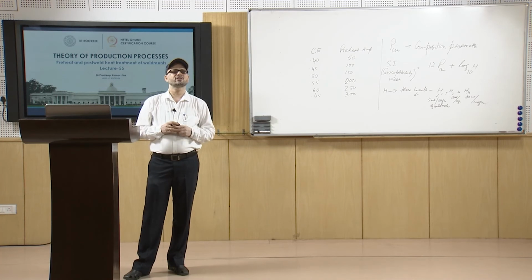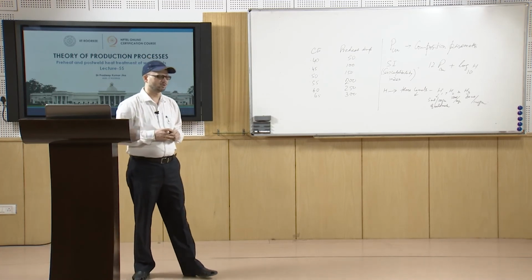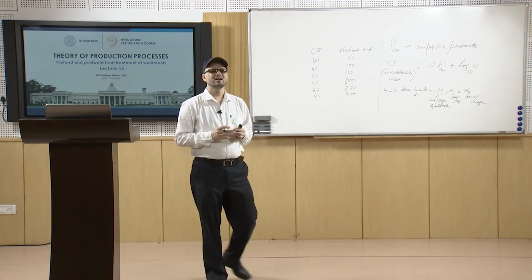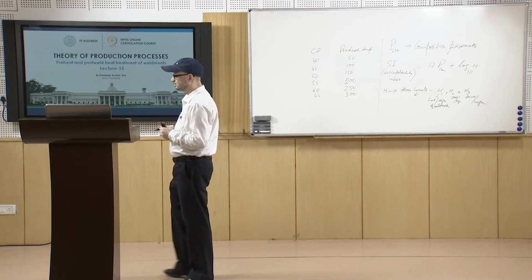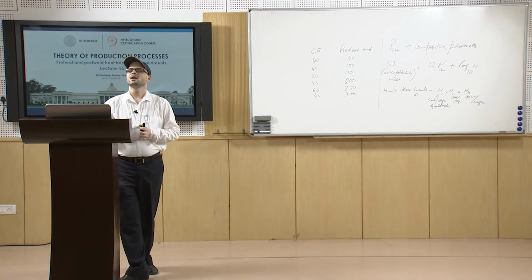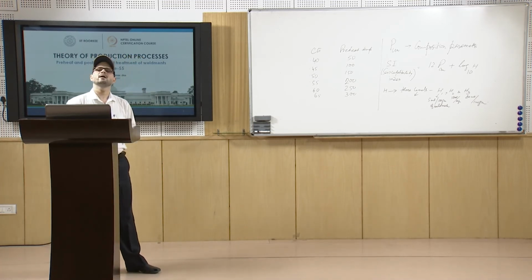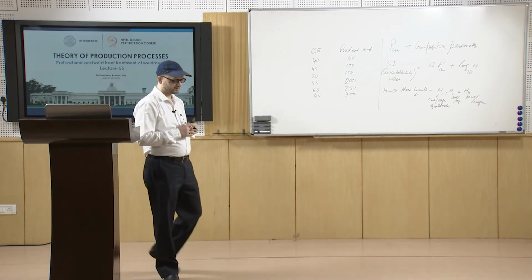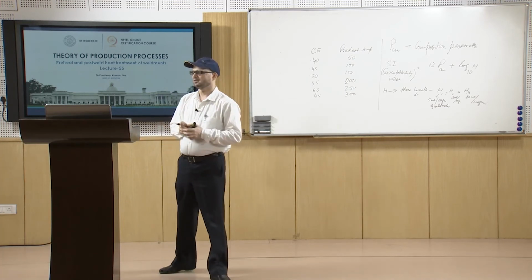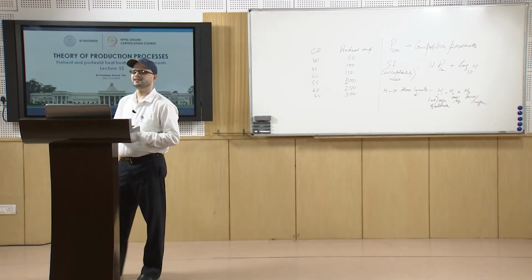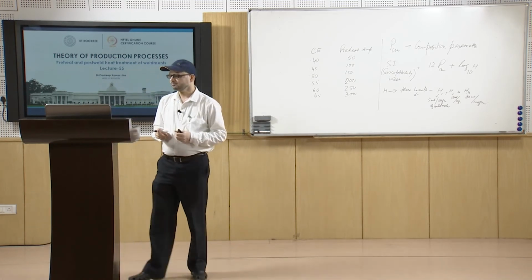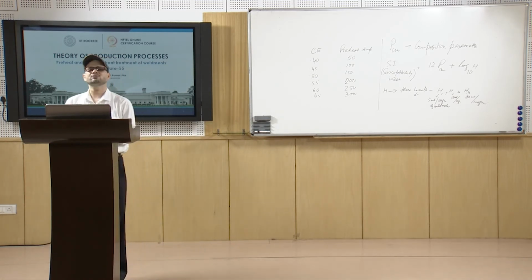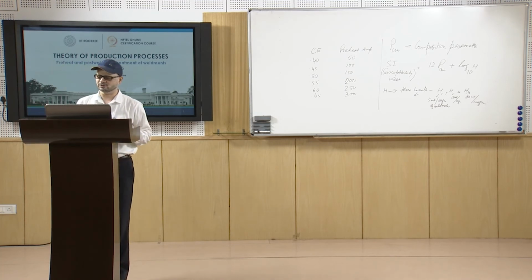Then local low temperature stress relieving is also carried out. Basically, the purpose is to relieve the stresses. Other methods in post weld heat treatment are quench annealing, normalizing, hardening and tempering. In the case of annealing, you have to take certain precautions.